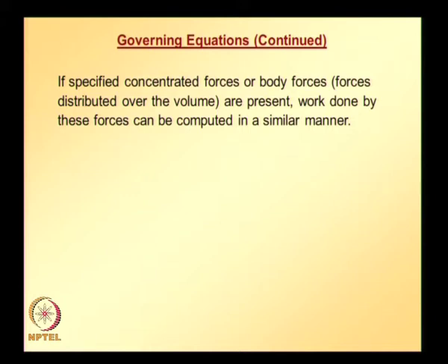So, we looked at how to evaluate strain energy and also how to evaluate work done by the applied forces. So, we are ready to derive finite element equations for the 3 dimensional elastic problem. Before that, we need to make a choice of the type of element that we are going to use for solving the 3 dimensional elastic problem. Here, we are going to look at the 4 node tetrahedral element, which is basically a linear element, and also the 8 node linear solid element, commonly known as brick element, and the 20 node solid element with curved edges.